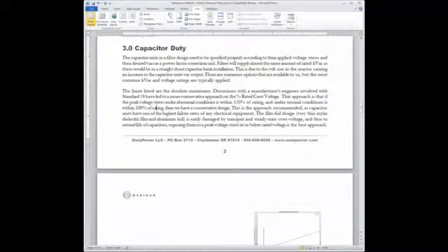One last thing: capacitors are one of the most failure-prone pieces of equipment that we will apply. I remember doing a harmonic filter design for a large aluminum smelter, and we were going to be putting in 5 20 megavar harmonic filters. The published failure rate on the capacitor units basically said we were going to have 6 failures per year. That's a lot. The guys are going to be going out there, de-energizing the filter, pulling a can out and putting it back in.